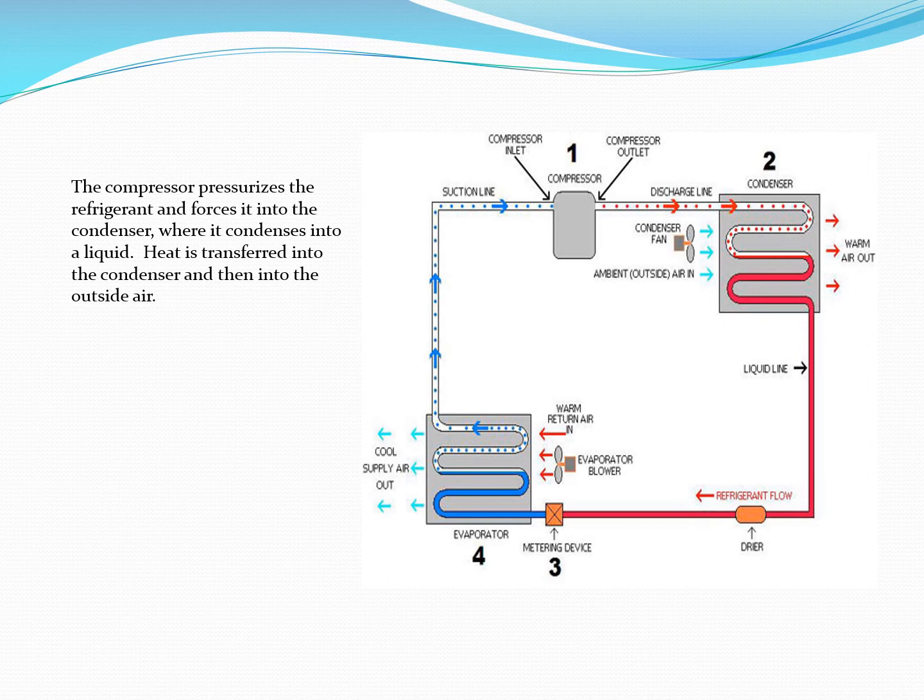If you're looking at the diagram, you could draw a line right through the compressor and right through the metering device as your dividing points of the system. So that means everything that's on red, discharge, high pressure. Everything in blue is low pressure or suction. So the compressor is sucking from the suction line. It's pumping or pressurizing everything in red.